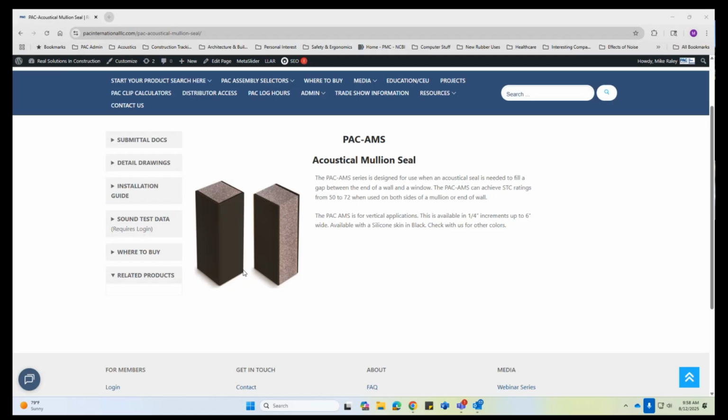Constrained layer damping is when you have two layers, typically two layers of drywall next to each other, moving microscopically relative to each other. The constrained layer damping resists that motion and takes some of that motion and transforms it to heat. So it takes some energy out of that movement. Typically, the constrained layer damping materials, like the engineered drywall or the goo that you can put between two layers of drywall, tend to work best at high frequencies. It doesn't do much for mid and low frequencies.